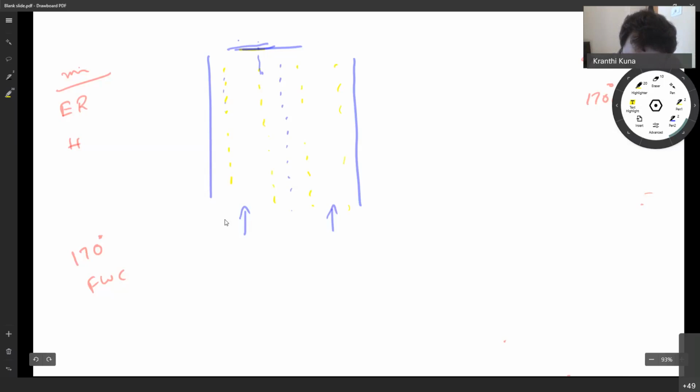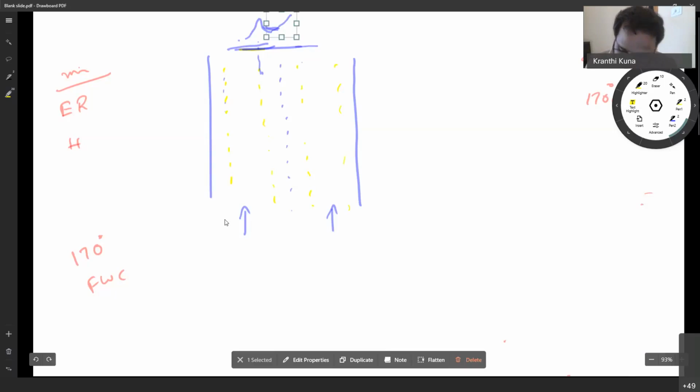The distribution will be something like this, with some standard deviation, as I was saying, of around 1.5 or something like that. And some vehicles might be wandering. Not all vehicles in this lane will stay in it. Some vehicles can go into the other lane as well, isn't it? During wandering. And some of the vehicles in this other lane also have some distribution, something like this.